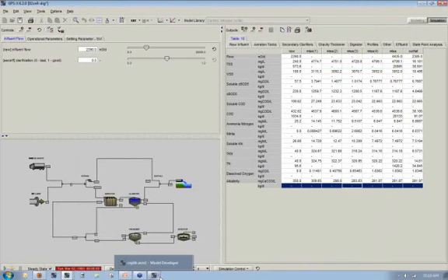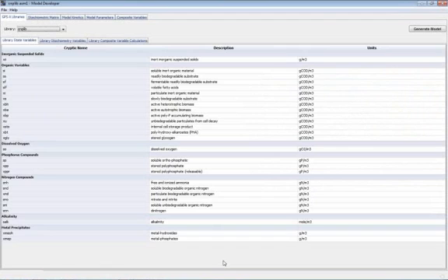Okay, so I'll briefly mention Model Developer while I'm here as well. This is a tool that is really for people who are doing advanced activated sludge model development down to the level of editing the equations that describe the different types of biomass growth and hydrolysis and conversion of nitrogen and carbon, and want to be able to make edits to those models such as ASM1 and ASM2D and create their own models. So this is a tool that we always have had in the past in GPSX. It was a spreadsheet that allowed you to generate new code and new models right in our software. We have now rebuilt this, and it is now the new version that we're using in-house here at Hydromantis.